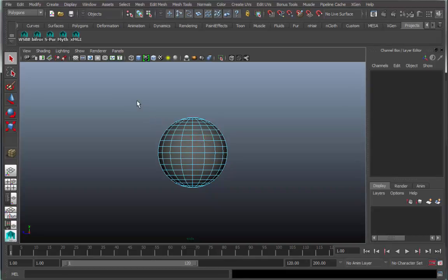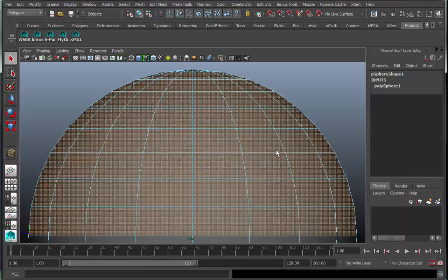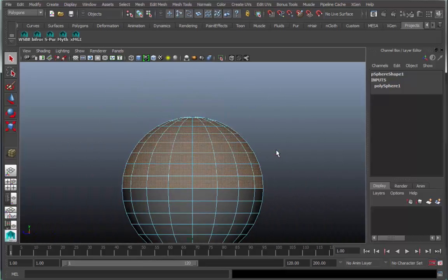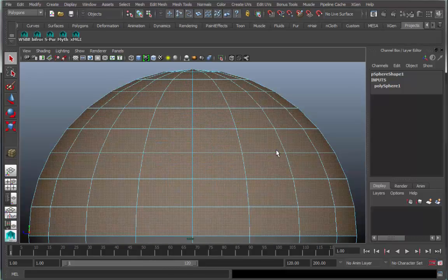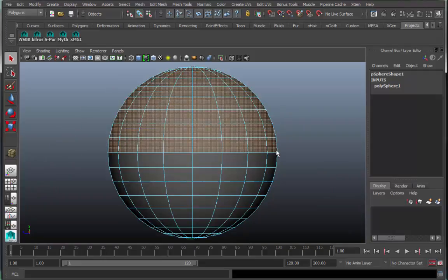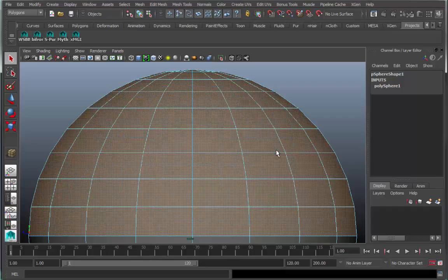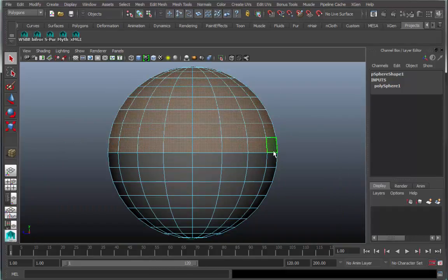Now, the other advantage to this mode is that you're allowed to draw a selection square, which is exactly what we want to do for just the upper half. And with the upper half of those polygons selected, here I am pressing F so I can frame what I have selected. The hotkey for frame all is A. The hotkey for frame what you have selected is F. And you can see it works in component mode as well as object mode.